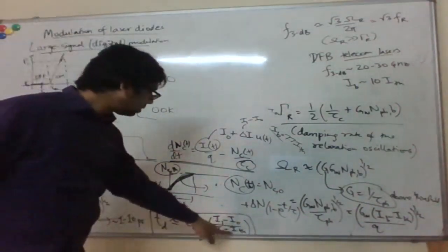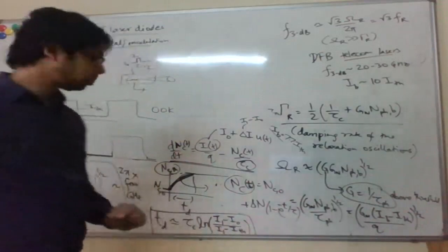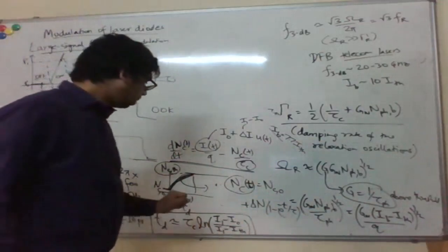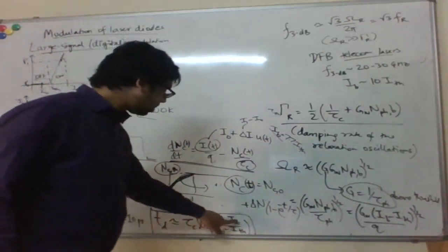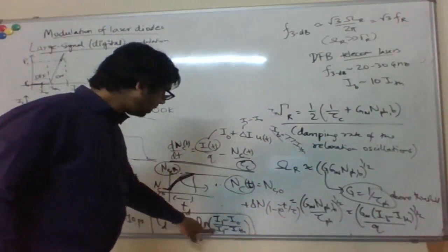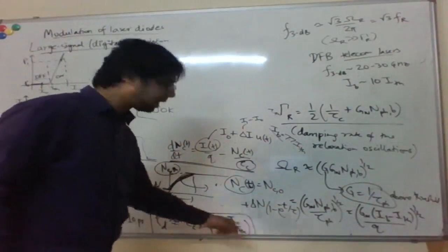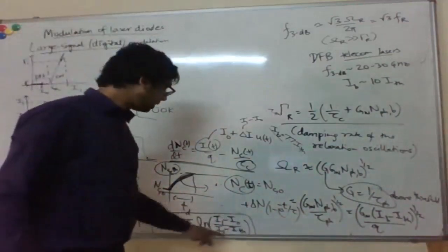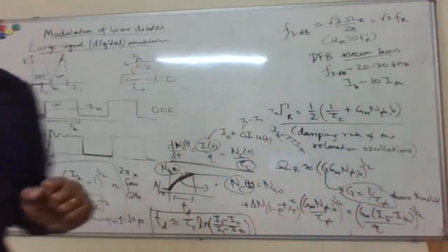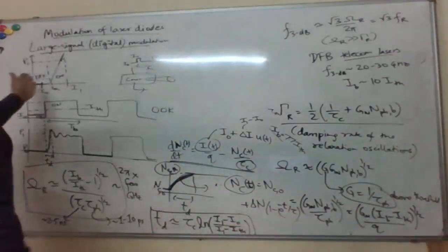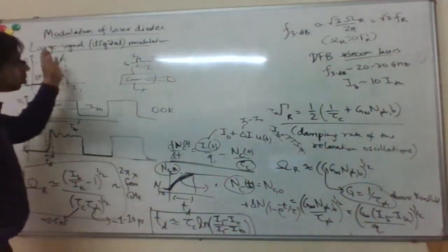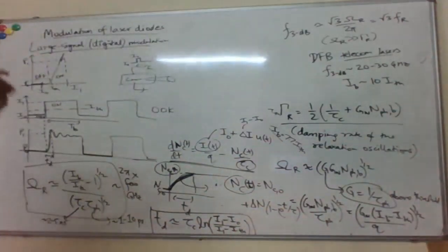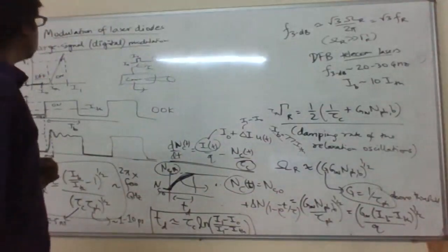In that case, you can see that the rise time will be quite slow. If I0 is 0, you basically want I1 to be much higher than I threshold, to make this small. And typically you can't go very far beyond I threshold. Maybe you can go 5 times.